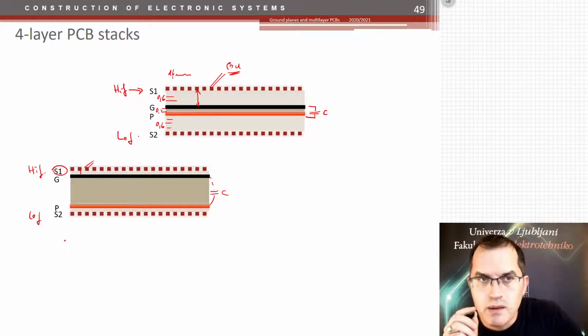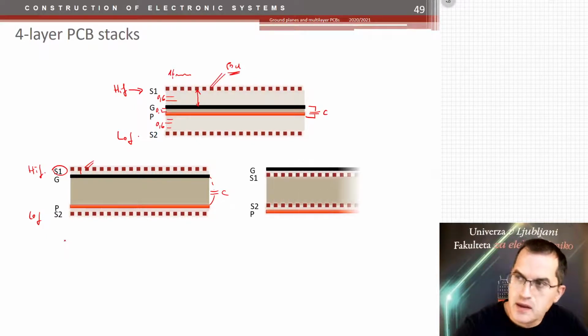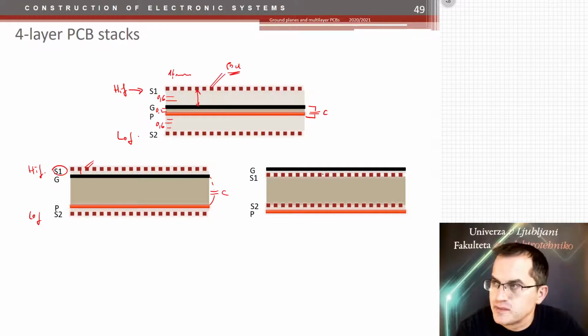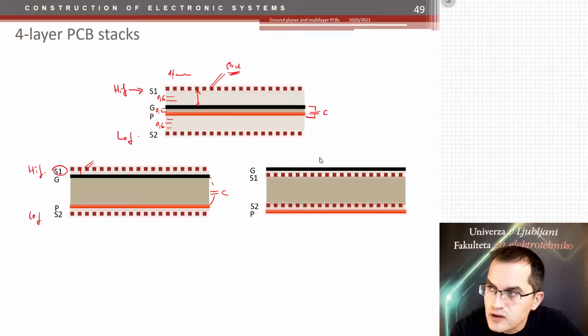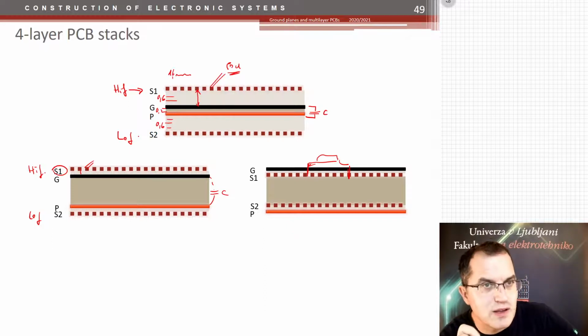If you want to make a 4-layer PCB that has, how to say, an even lower EMC footprint, you can make a layer PCB like that. So you have a ground plane on top and a power plane on bottom, and then you have signals in between in a sandwich, just the opposite. Well, in this case, the ICs on top cannot be connected directly between each other. The components on top have to be connected via wires. So you need a lot of wires, which is a disadvantage.